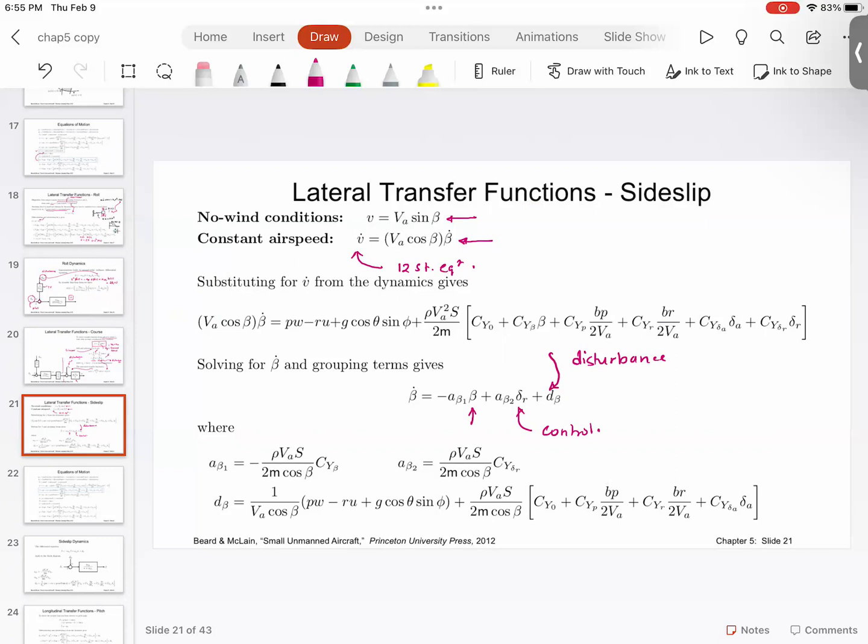So the mathematical jugglery that I talked about, exactly the same thing happened. You combined all the terms. Then you had some nonlinear terms. You converted that, you say that term is a linear term, and then you treat that as a disturbance, and you find out all these constants. So now understand, this disturbance term is a very complicated term that is arriving here. Everyone understood this? So what would my control effort do? The control effort would control the dynamics and cancel out the disturbance.